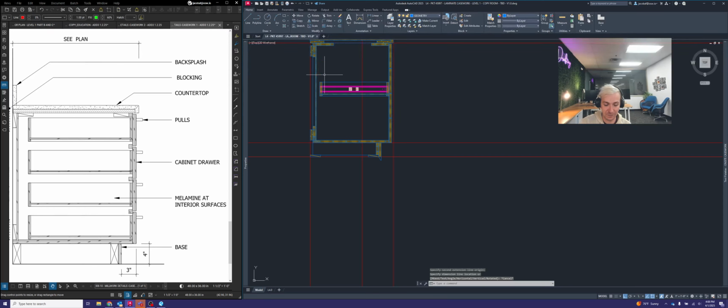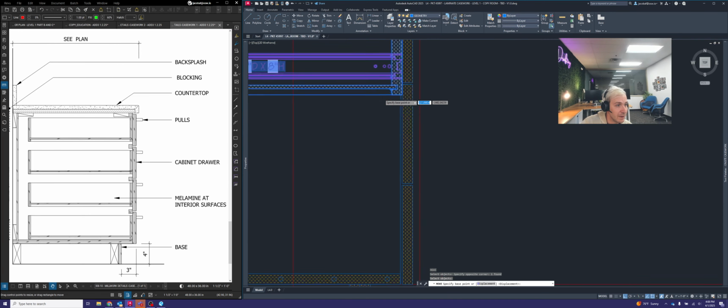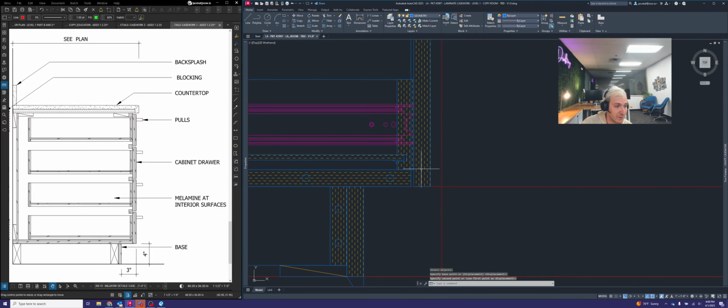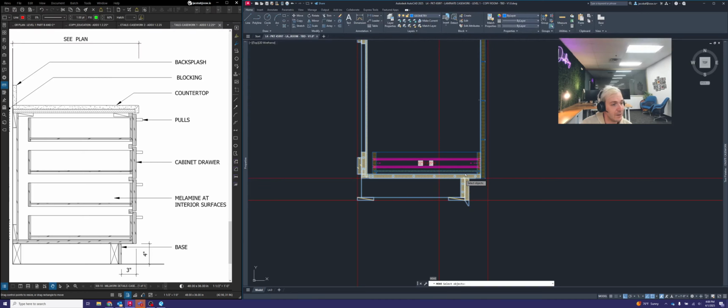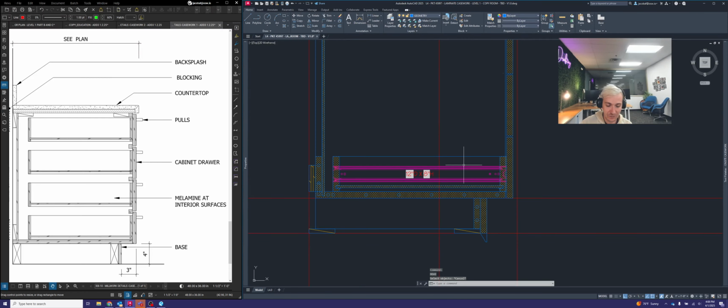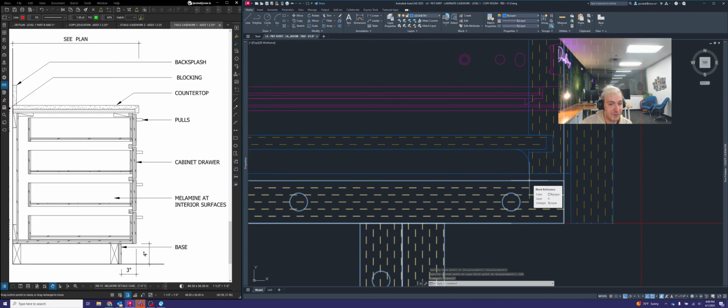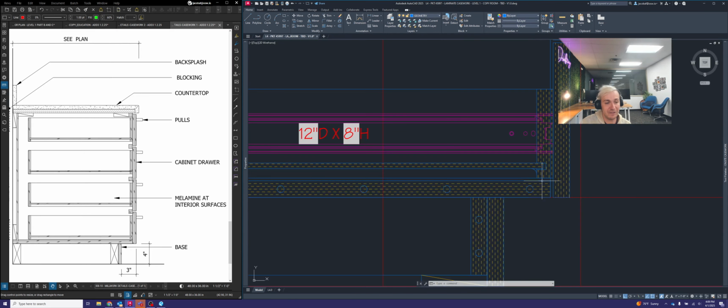Right now we're at 30 seconds. That's great. That's within our standard. And we are at increments of 2 with our drawer box. So we are within standard there as well. I kind of just used the move command. I lowered this drawer box down. I'm going to raise it up now 1/8 of an inch. 1/8 of an inch is the bare minimum that you can do between the bottom of that drawer and the underside or the bottom of your inside of your cab.